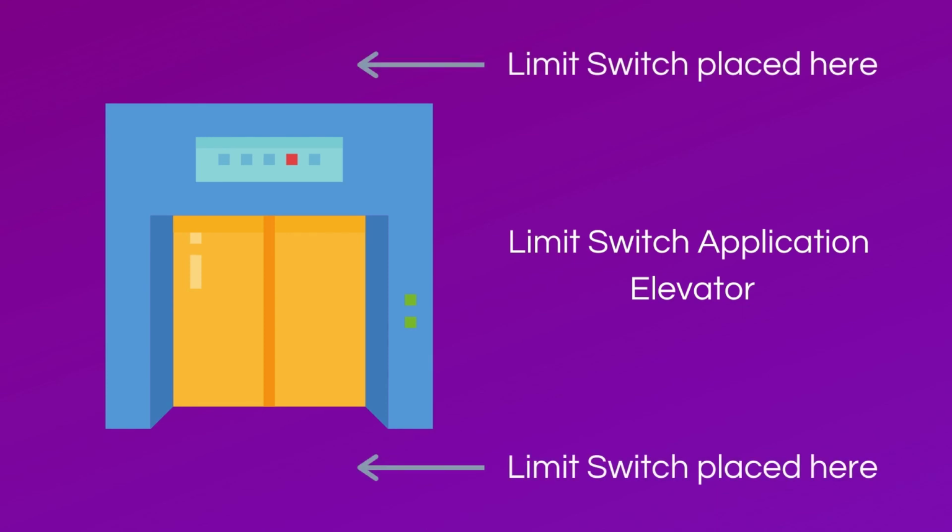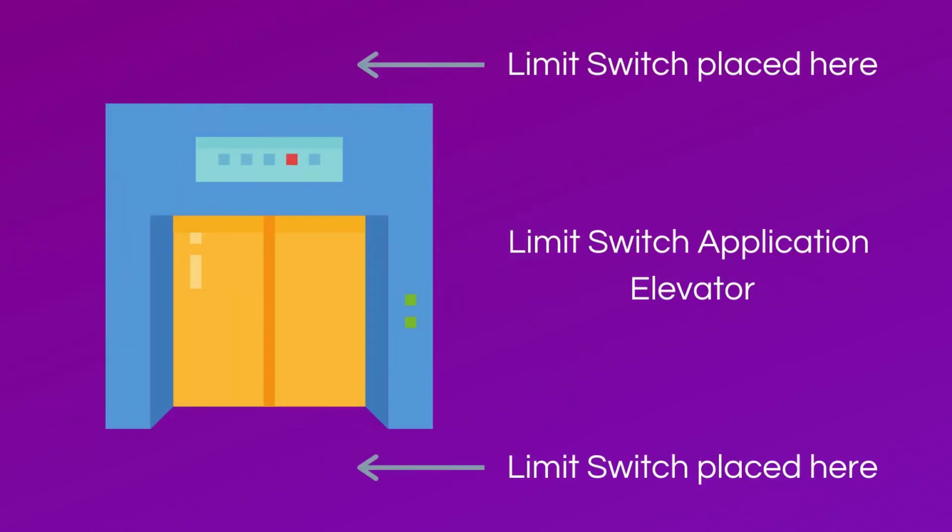On an elevator shaft, a limit switch is placed on top and on bottom. When an elevator reaches the bottom, the limit switch is actuated, preventing the elevator from crashing into the ground. When it reaches the top, a limit switch prevents the elevator from crashing into the ceiling. Essentially, a pair of limit switches keep riders safe by ensuring the elevator stays on track.